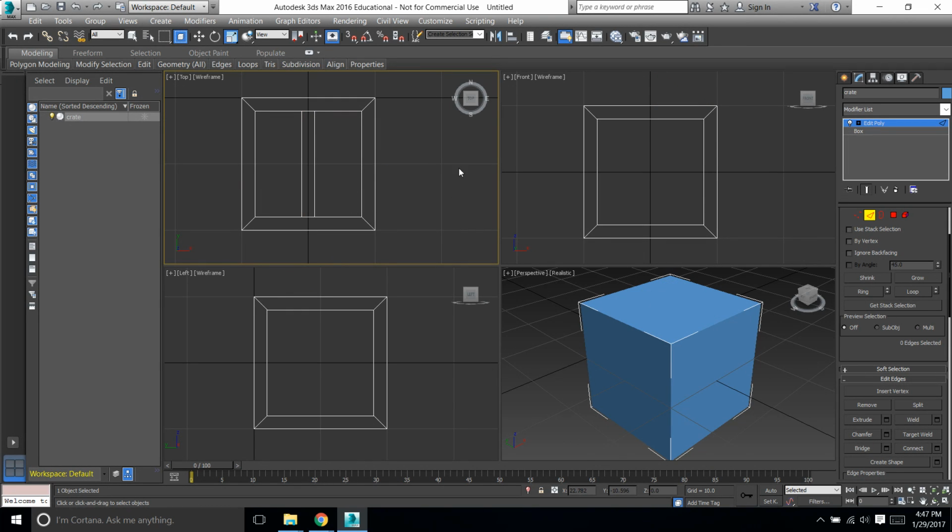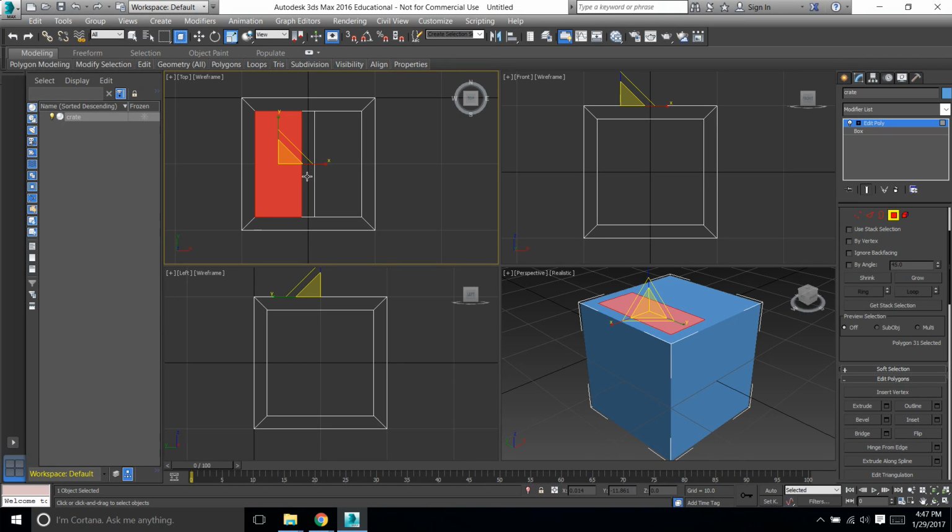Now sadly, we've got to do this 6 more times. So you'll have to do this 6 more times, but I will tell you that you can get this all done at once. And then once you go through all the steps, you're going to switch back to Face Tool now. And on the Face Tool, you're going to choose the insides. And if you'll hit Control, you can hit here. Now, if you have more faces, if you've done this on other sides, you can just keep hitting Control.